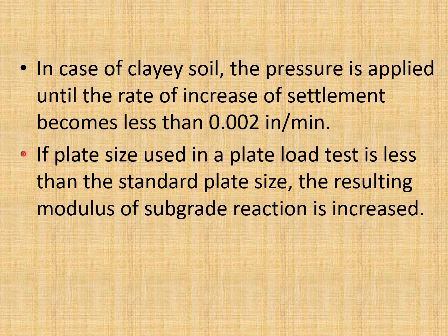Why is it so? The reason is that when you are using a small size plate in place of 30 inches diameter plate, so when you are applying the 10 psi pressure, it means you are going to apply a small force in that case because the contact area is less.